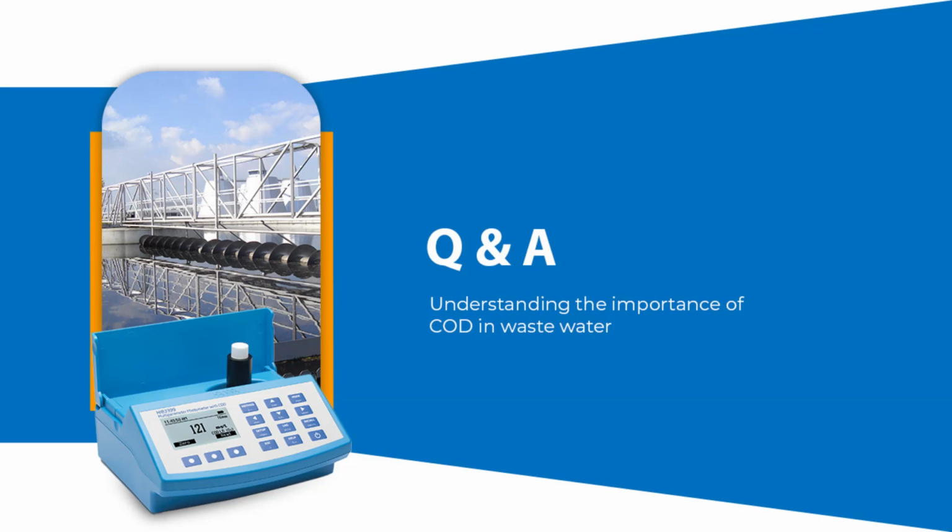What is the difference between COD and BOD? COD is chemical oxygen demand. It works on a chemical basis. We use chemicals like potassium dichromate, mercuric sulfate, silver sulfate, and sulfuric acid in an acidic medium, where all the organic compounds can be fully oxidized to carbon dioxide with a strong oxidizing agent under acidic conditions.